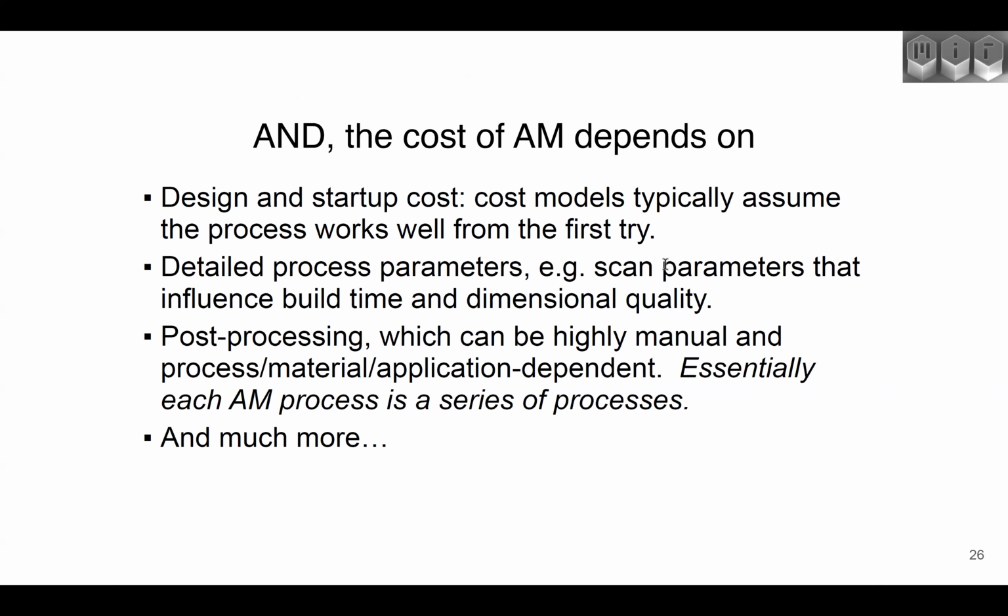And then last is post-processing, which is just to say there are a million ways you can post-process printed parts. It depends on your customer requirements. But again, there are going to be cost trade-offs there. There can be throughput trade-offs there. And in some cases, support removal can be really, really manual and really time-consuming. So even if it's not expressed in CapEx or anything else, it might just mean you have dedicated people, and that can add up quickly.